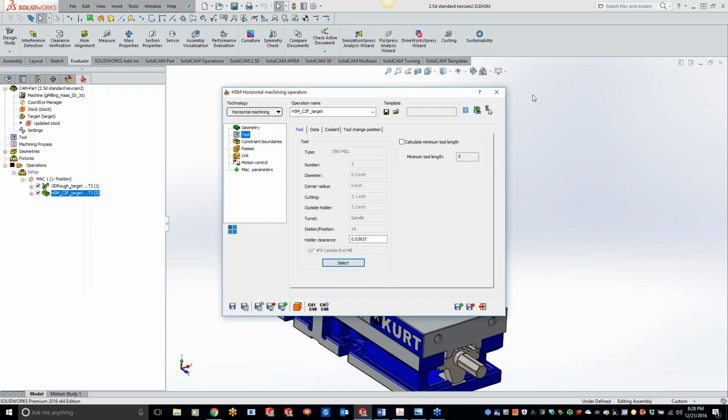Okay. So Kevin, as you're moving through this, I think there might be a relevant question on prismatic work on a 2.5D Bridgeport machine. Oh, absolutely. Yes. Not an issue at all. You will have to drip feed it just because the Bridgeports and some of the Sharp machines are pretty limited on memory. You can either get more memory, or, like I said, drip feed it. But it definitely does work.